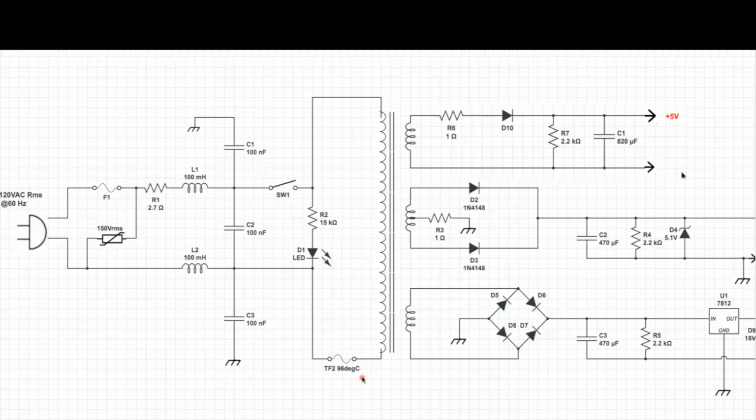So the manufacturer may say, I'm keeping the cost down. I'm going to take that EMI suppression circuit out, that line choke. It'll still work. It just might get interference from other devices. And depending on how hot the device runs, it may or may not have that thermal fuse. So these parts are in here to show the different things that we might do on the primary of our power supply to protect it, to noise suppress it, thermal protect it. All these optional devices that the manufacturer determines, do we need to put them in there or not?